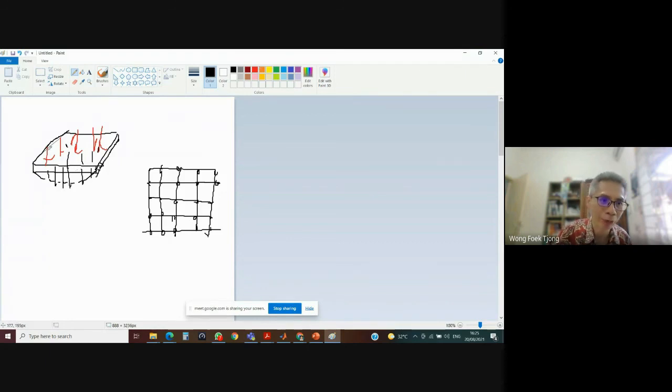By creating the finite element mesh, the displacement is only allowable here, at its nodes, not at every point. Because of that, it becomes a discrete model, since not every point can move freely. Only the finite element nodes can move. It is a kind of restriction to the original model. Does this answer your question?